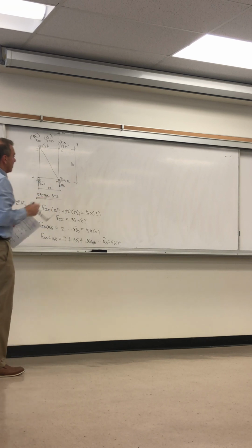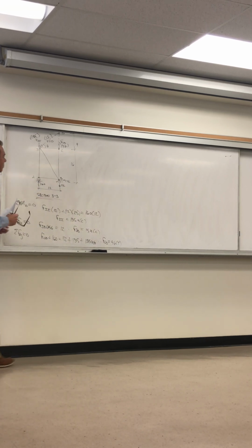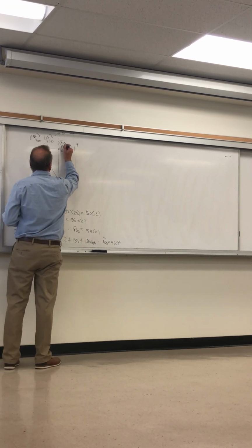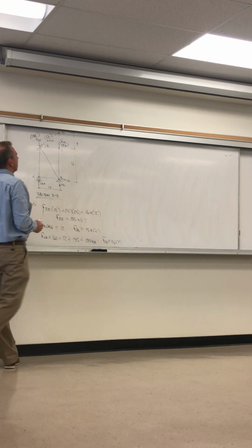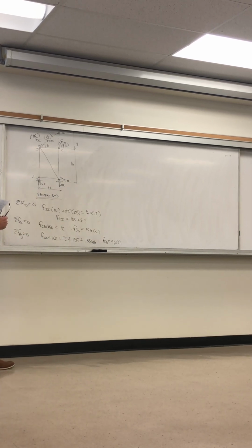Positive numbers, consistent. That means the way I drew it was the correct direction of the force. It's 96 kips in tension.